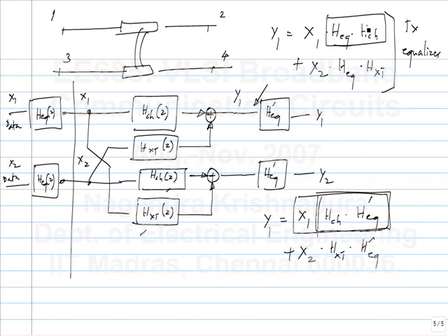So what is the signal that you get? It's the same. So it doesn't matter if you put it in the receiver or the transmitter. The response will be exactly the same. Because basically the bottom line is the crosstalk goes through the similar transfer function. So if you increase the signal, then the crosstalk also increases. That's why you can also not play around by increasing the amplitude of x1 or x2. Of course, we are operating under the assumption that both channels have to work properly, like x1 to y1 and x2 to y2. You can always make one of them better by attenuating the other one, then the other channel will behave a lot worse. Okay, both of them should work well.